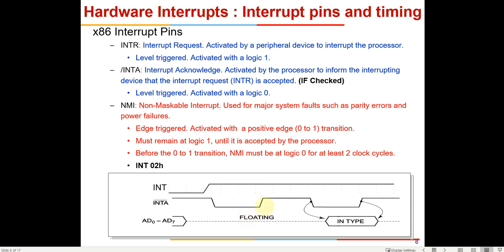We'll see that. So what the interrupt controller does is it is connected to various IOs, and it places one interrupt request to the microprocessor whenever it receives an interrupt request from one of the IOs. Once the microprocessor tells, okay, I am ready to receive the interrupt signal, then depending on from which input IO port it has received the interrupt, it will synthesize the type of interrupt which is to be done, and it will be kept ready.